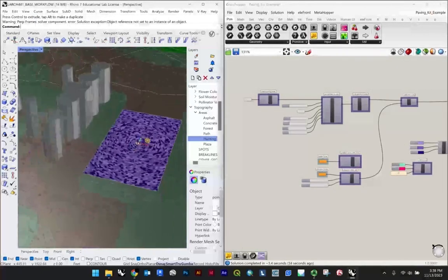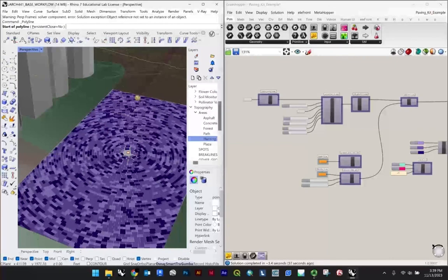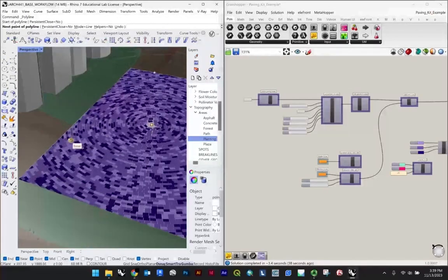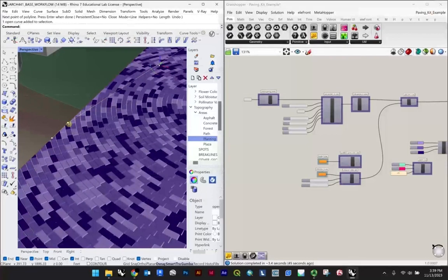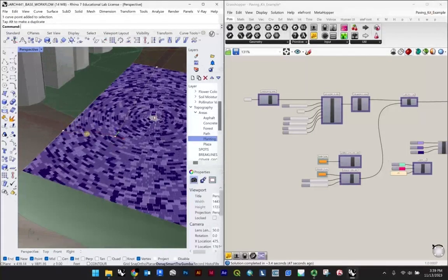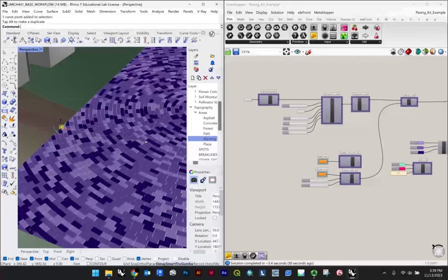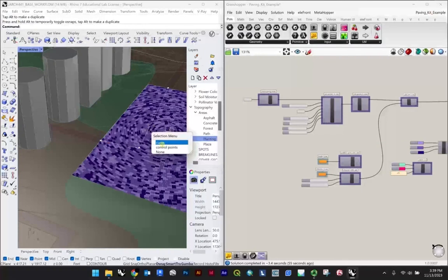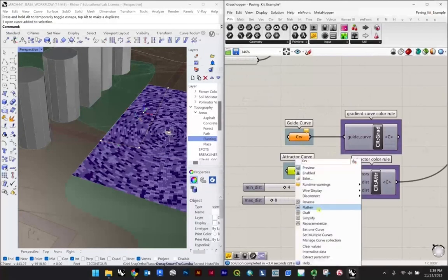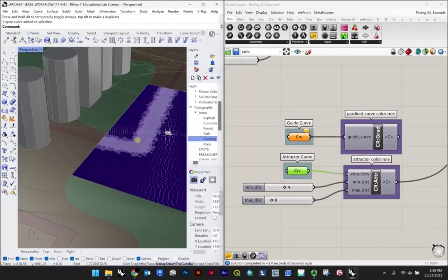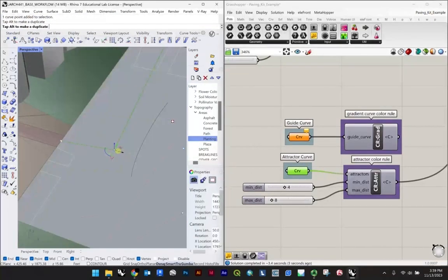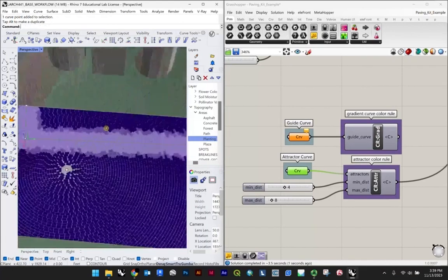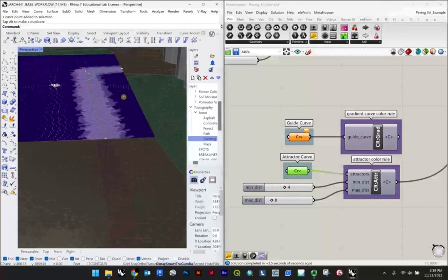So if you wanted to, let's say I was interested in starting to dictate through my paving design a kind of implied path through this otherwise flat field condition. I could draw something like this. And let me just pick that curve and I'll set that here, right click, set curve. So now what's kind of nice is you can start to create these implied pathways just through the paving design, right? So it's all flat, but you can start to connect these.